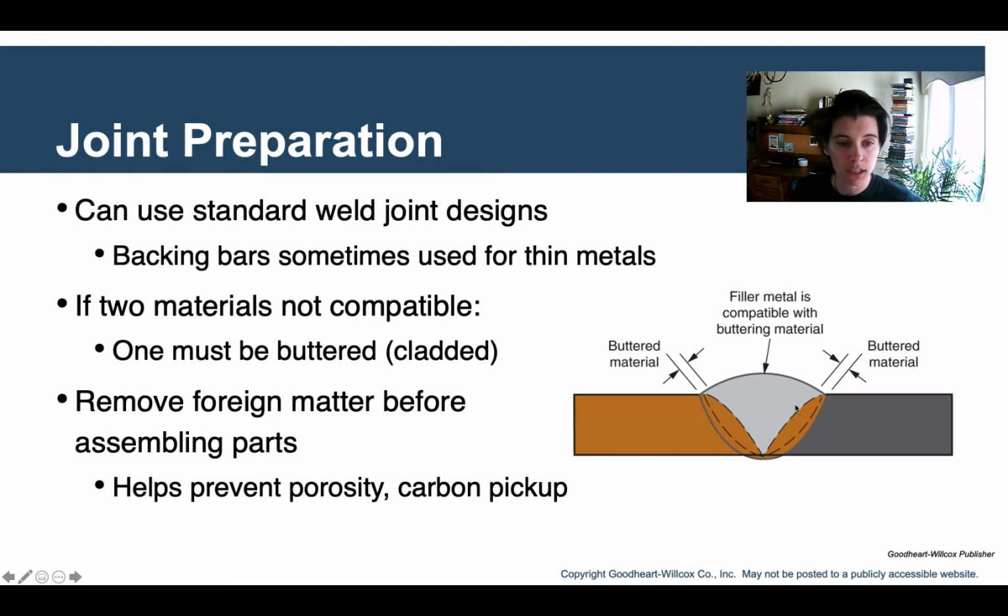And then on this side, you'd use a different alloy that's compatible with this base metal and also this main filler metal. And you'd surface that, and then you fill the whole thing in with your filler material. That's called buttering or cladding.